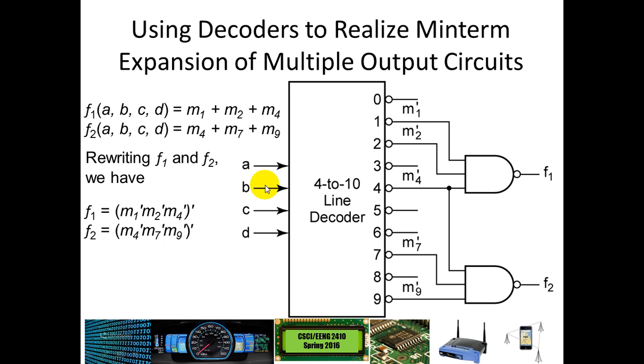In this case, you can choose which of your min-terms you want in a function, and you can put them together. This is an inverted decoder where the active output is logic 0. So you'll notice that if you put a NAND gate with each of these inverted outputs here, that's effectively like putting a bubble on the input right here, which is taking this and making it like a NOR gate, and then if you invert the output it makes it like an OR.